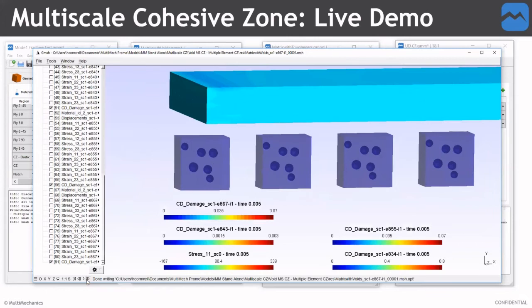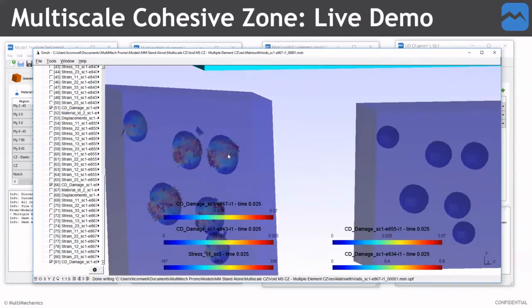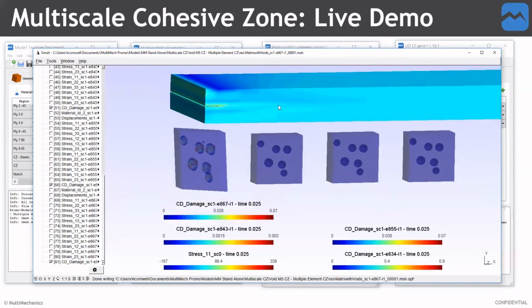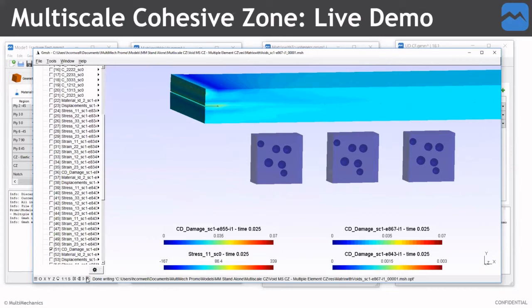We'll go step by step, and we'll see how the first RVE experiences a lot of strain very early on. We start to see some damage occur at the edges of the spherical voids. And then we finally see some failure going on within the voids. Now, this hits a certain reduction in stiffness within the material. So after that, the RVE will be deleted and the crack will be considered passed through it, and this RVE will no longer be relevant. So I'll delete that. Then as we keep progressing through, we see that this next RVE, which is located closer here, starts to undergo some strain. And then eventually the crack will pass through and it fails.